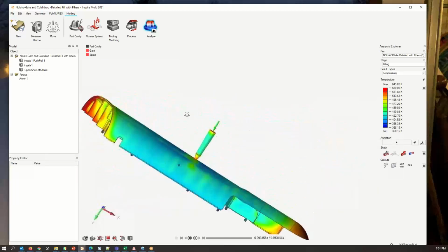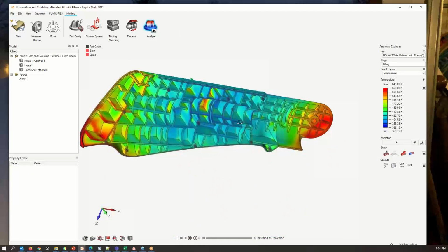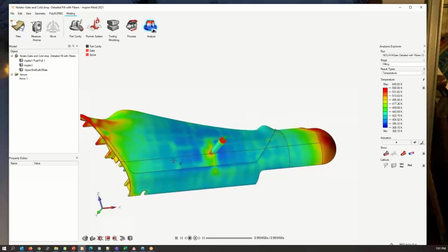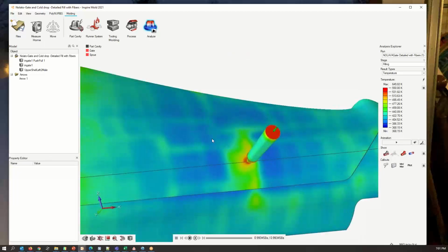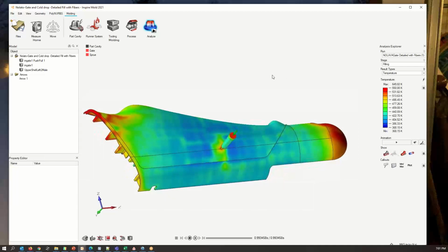And then, as in a packing analysis, I can look at trying to improve the density so the density variation, particularly the density variation, doesn't change greatly over short distances, because that will be the thing that causes those sink marks. Sudden changes in density. Thinking in terms of physical gradient in space. All right, so that's kind of the biggest things there.